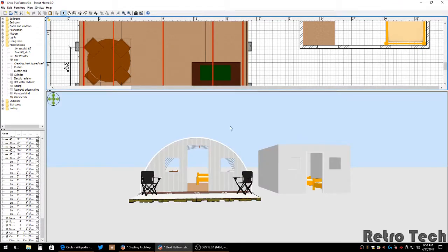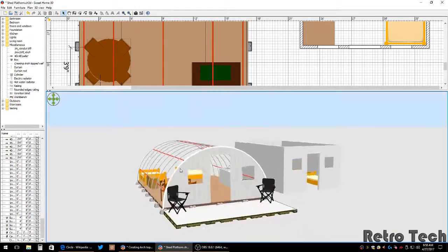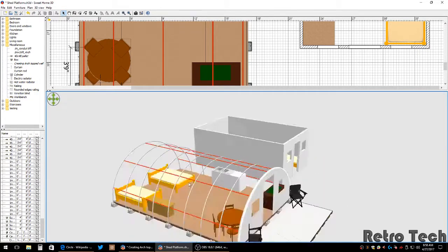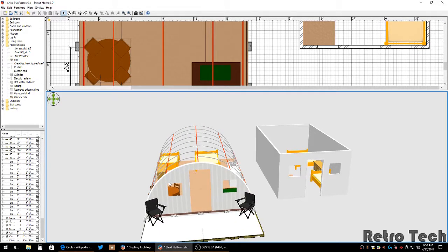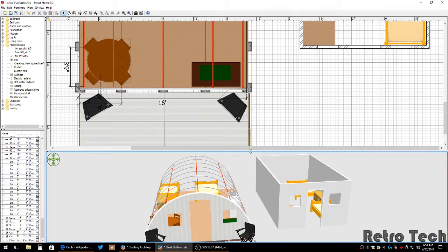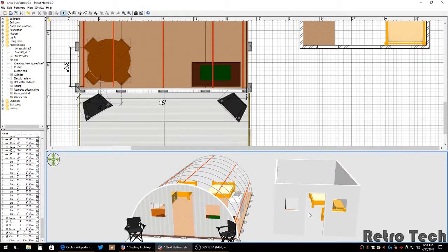And now, when we look at our 3D representation, I now have a solid, curved, arch-topped wall. Now, for the windows and the door framing, I can come back using the box tool, and I can create a myriad of options to make it look like a casing around that door just using the box option in the software. So that's it. That's how you're going to do that.